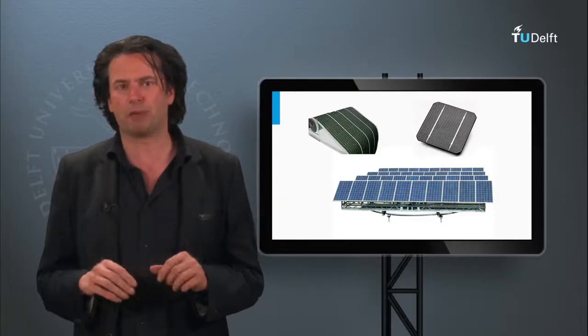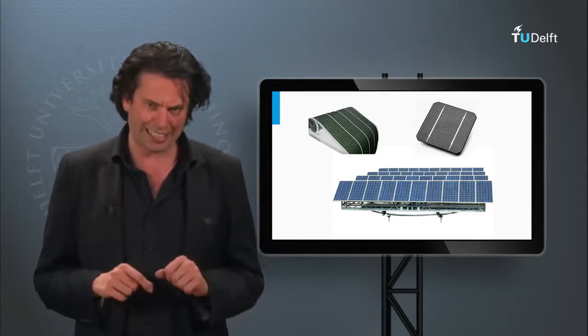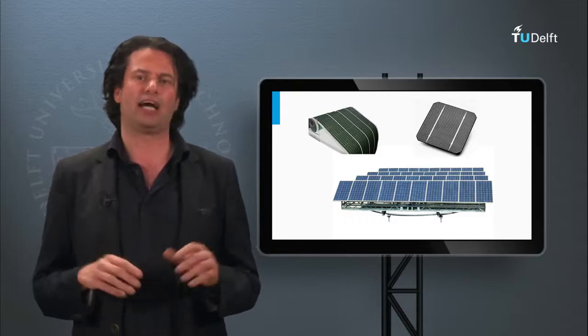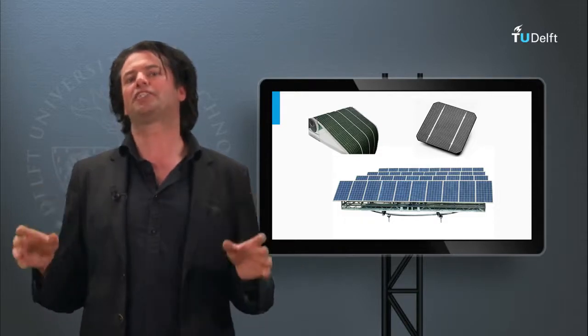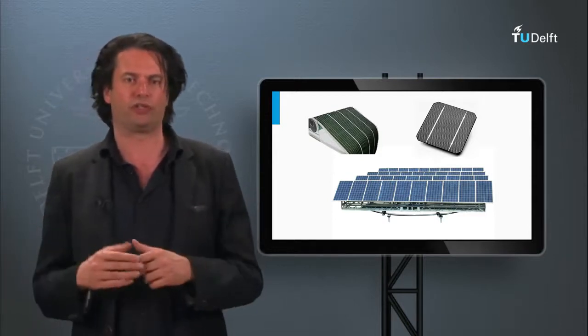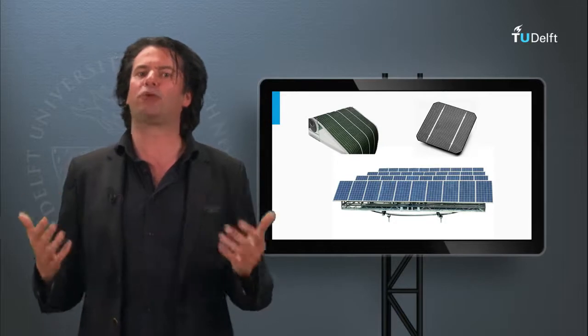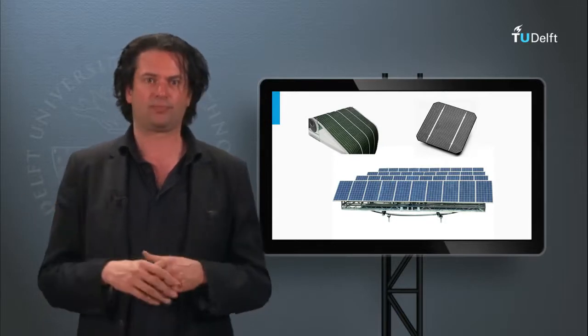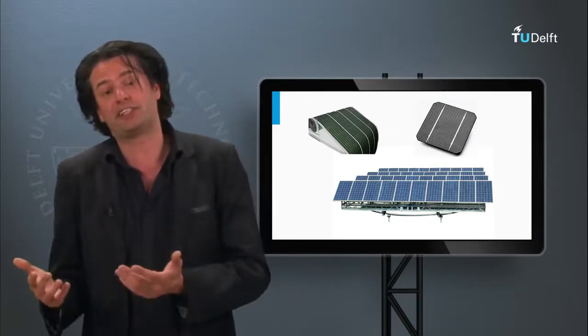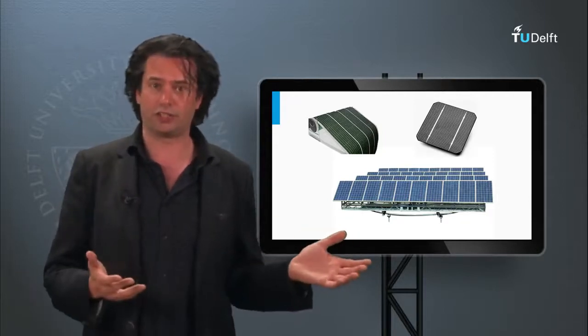More PV technologies are being analyzed at the Delft University to understand the extent of the temperature effects. As said before, the amorphous silicon technology show very low temperature coefficients due to their high open circuit voltage. This means they would show a better response under high temperatures. However, their efficiencies are far lower compared to some of the best crystalline silicon technologies.